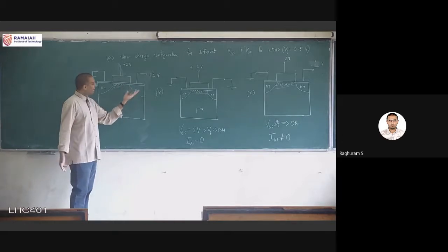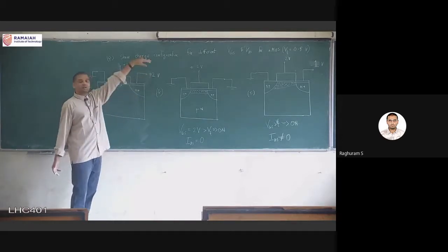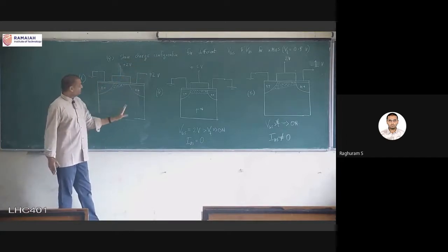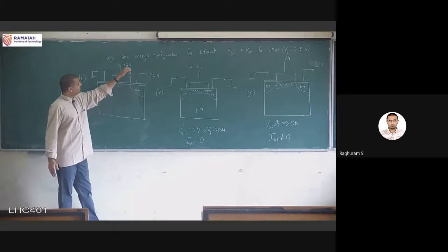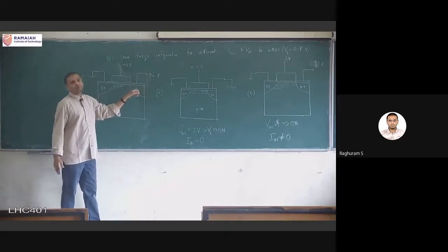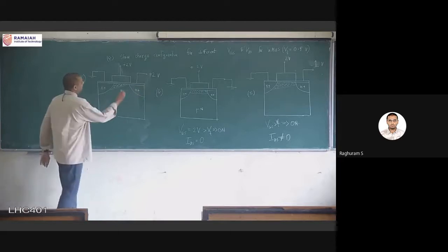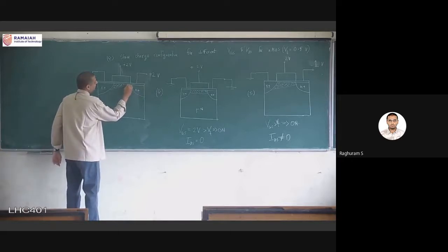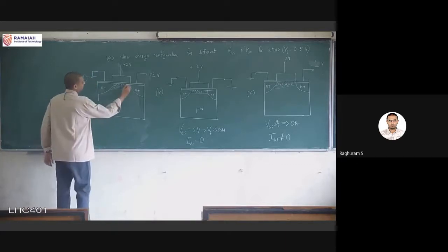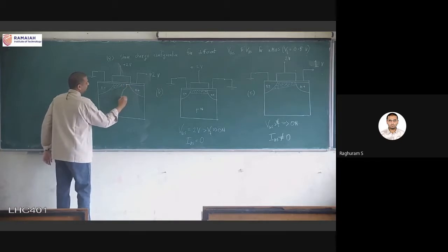Why is the reason? Again, now we have increased it to a higher value from 1 volt to 2 volts. So they don't have any doubt. Any electrons attracted to this region by this plus 2 volts, they don't stay in this region because they see another plus 2 volts here and they jump into the drain region. And that is why in this very small region here, we don't see any electrons collecting, and this particular point is called as pinch off